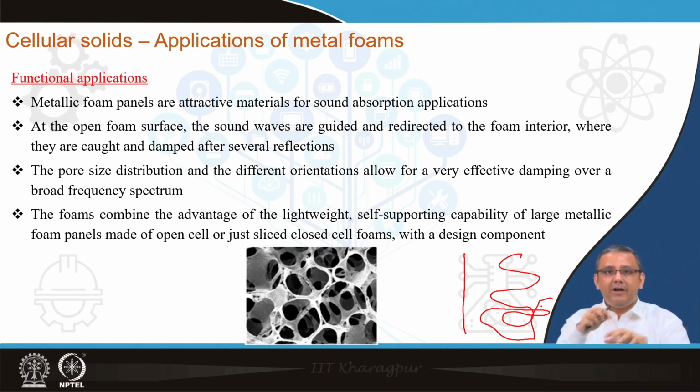Because of this continuous interconnection between the individual edges, whenever sound energy is incident on the open cell foam surface, it undergoes multiple reflection and interaction, and by doing that the sound energy loses its energy. This way the open cell foam is an ideal material for sound absorption, and it has been used very often.